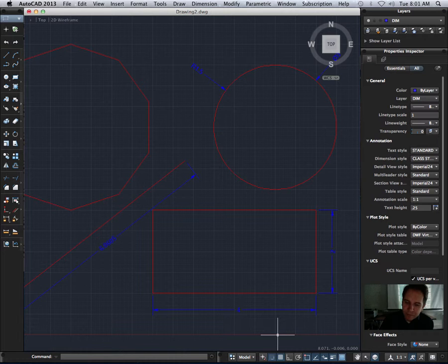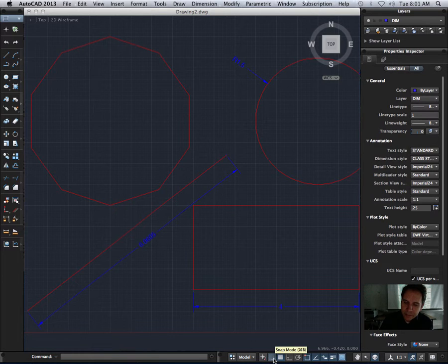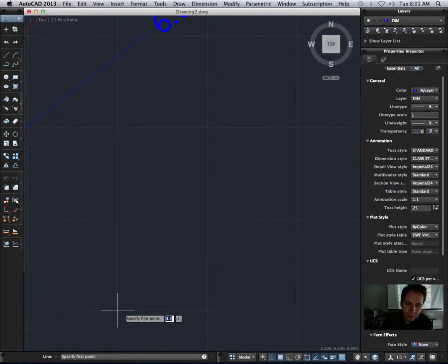And then we have a number of drawing aids here at the bottom. The first one is to snap to our grid line. So you'll notice when I select, say, my line tool, as I move my cursor around, I'll zoom in a little bit, you notice it jumps from intersection to intersection on these boxes here. This is snapping to our grid, which is a nice way to